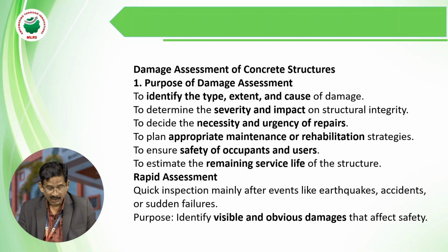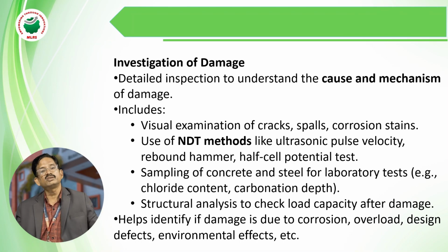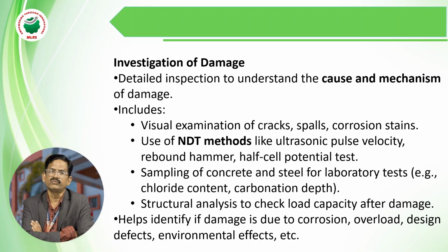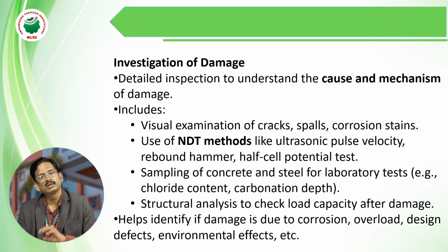What is the purpose? Identify the visible and obvious damage. Next, investigation of the damage. How to investigate the damage? Visible examination of the cracks. If there is a beam, slab or column, automatically some cracks will be visible to the naked eye. Or sometimes you use non-destructive test methods.